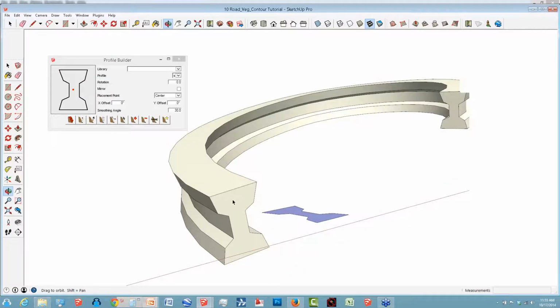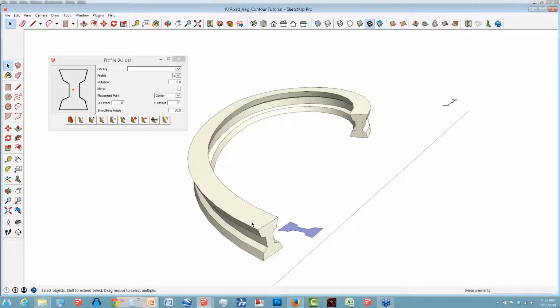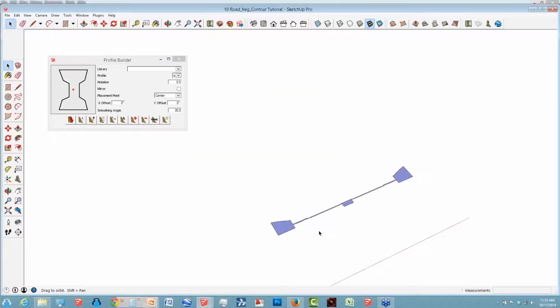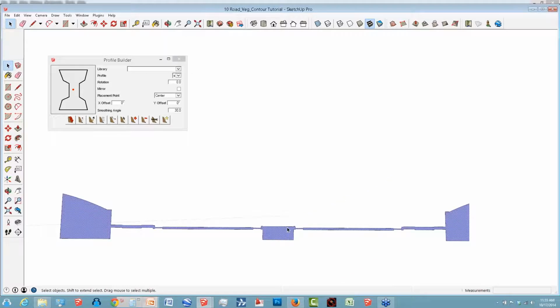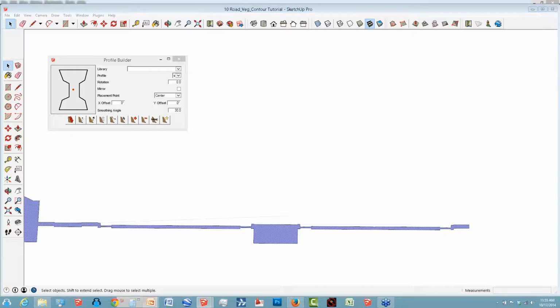faceted arc or curve. Just to show you how this all works together, because what you'll end up doing is taking your extensions and stringing them together. Here I have a very simple road profile. So this is a road section, quite literally. I have 2 12-foot lanes. I have a curb and gutter. You're going to see it as it catches up here in a second. I have my road. I have my striping. And I did draft this section in a very specific way so it can be extruded along using Profile Builder to create a road.